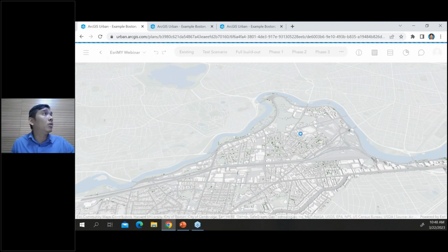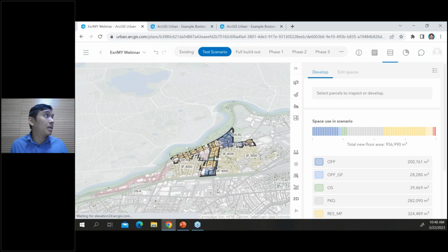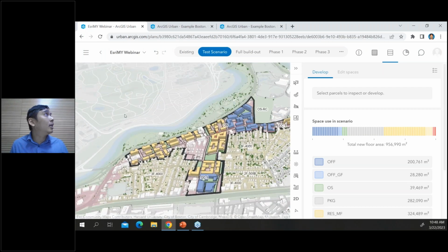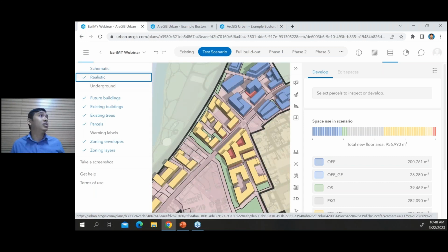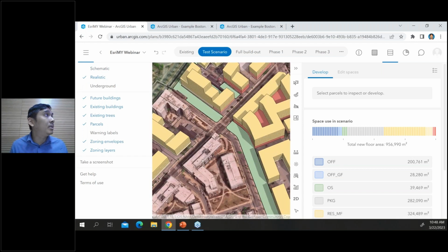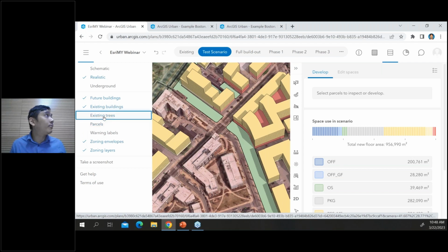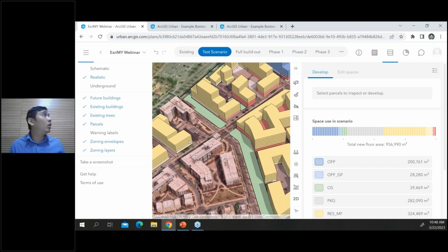So we will show one particular area where you have created a scenario in which you are planning to redevelop something. So here, for example, I would like to see the base map as imagery. I can change it to imagery, so it will give a better representation of the area. So the imagery will be embedded on top of the schematic. You can use it the same as a layer, so you can turn it off if you want to have a better view during your alteration process.